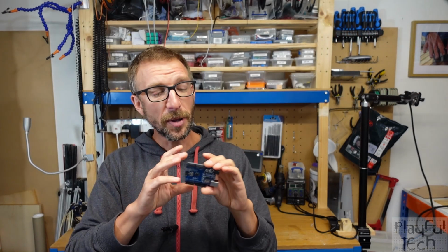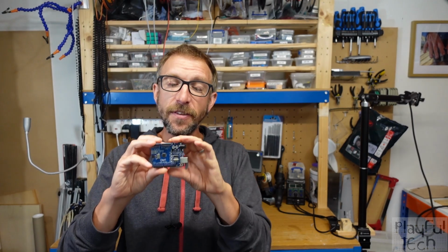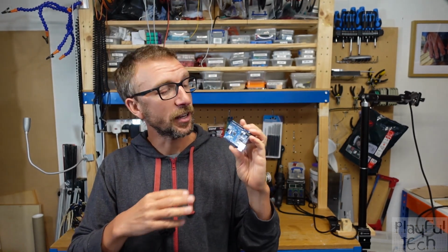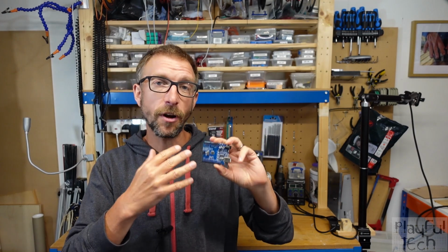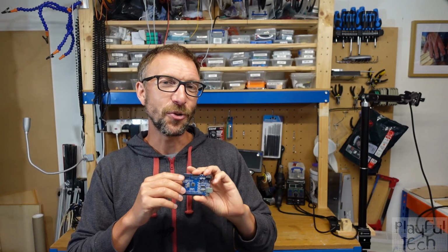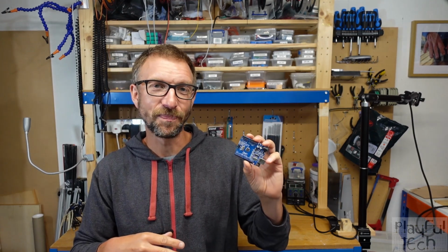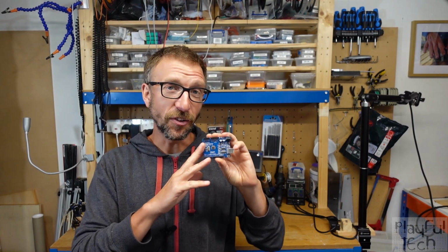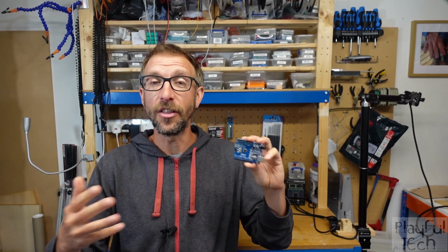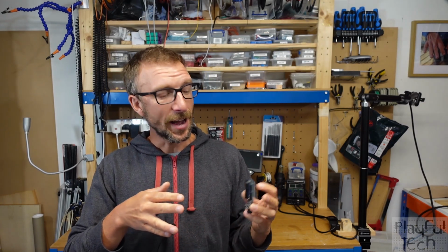Now, setting a GPIO pin as an output is how you get your microprocessor to control other devices. If you then write a high signal to the pin, it gives it a positive voltage, and that's going to cause current to flow through any connected wire through to ground. And that brings us onto the question of voltage and current that will flow through that connected device. So, just as microprocessors have different logic levels, so too do the other devices that you might connect to their GPIO pins. LCD displays, programmable LED strips like NeoPixels, and most motor driver circuits operate at 5 volts.